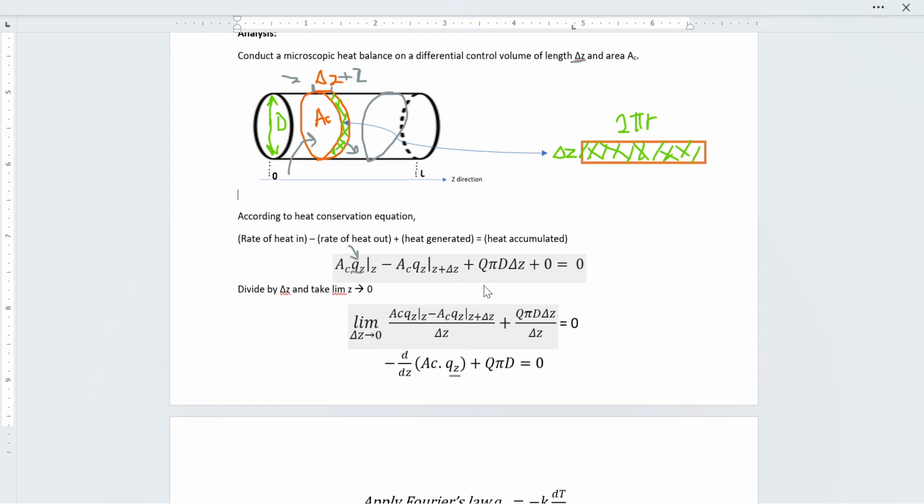Now this isn't the only thing that's happening. I am also applying a heat on the lateral surface. So on this surface I'm also applying a heat, with the flux Q, but for that flux the area is not this. I'm not applying the heat in this direction. No, that's not the case. I'm applying the heat in this direction. Now for this, the direction in which the heat is applied, the perpendicular surface area is going to be different. And that area is highlighted in green over here.